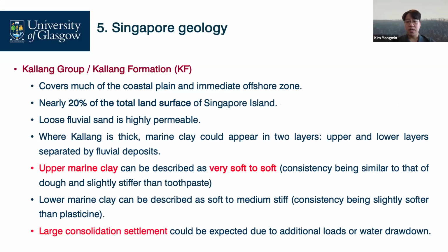But fortunately, the lower marine clay can be described as soft to medium stiff clay. But these clay soils exhibit large consolidation and large settlement due to additional load and water drawdown.